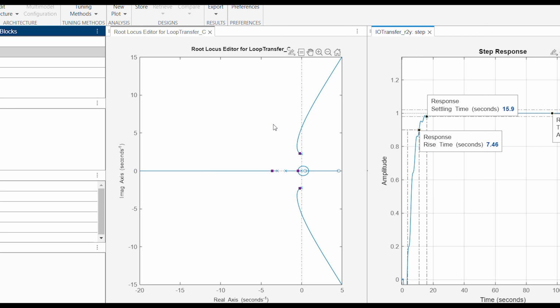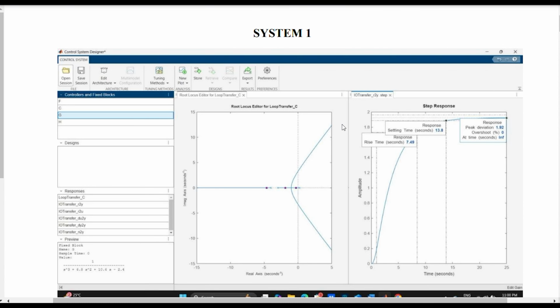The value for overdamped is between 0 and 2.079, for critically damped K equals 2.079, for underdamped it is between 2.079 and 5.7146, and lastly for undamped K is larger than 5.7146.